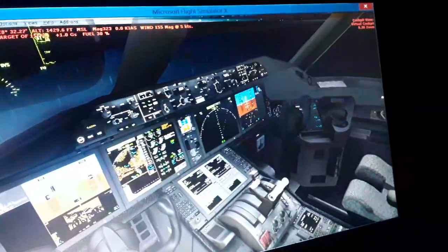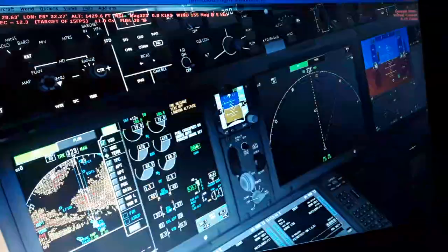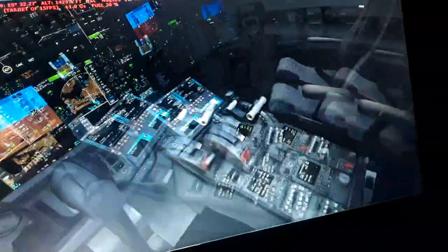maybe I'm gonna make the engine start demonstration and set up the flight plan right now. So you're gonna see the engine start demonstration. I'm gonna come to the flight controls here. I'll first show you the flight controls, how to control the flight controls using the side stick. Use to control the horizontal tail, to climb and descend, to bank roll left and right, and also to use the rudder pedals for the vertical rudder and the nose wheel steering.